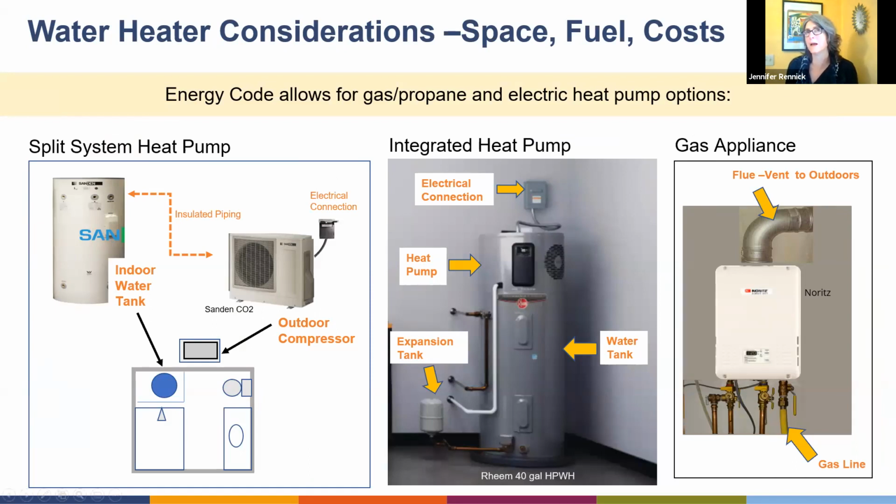Because a lot of times, think about it, if it's an existing house and someone's tank type heater goes out, well, they've most likely already got gas there. They need hot water. It's just kind of a no-brainer to put a tankless unit there if the gas line is large enough to accommodate that tankless heater.